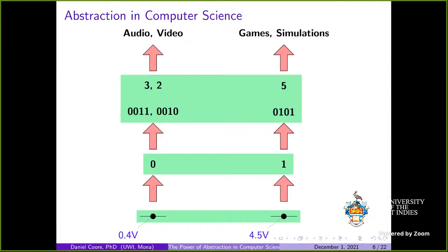It happens to be configured in such a way that when you put a low voltage on it, one of the voltages within that range I just said, below the low threshold, its output happens to be a voltage in the high voltage range. And so abstractly, how we regard that is when we put a 0 in, what we get out is a 1. It also happens that when you put in a high voltage, you get out a low.